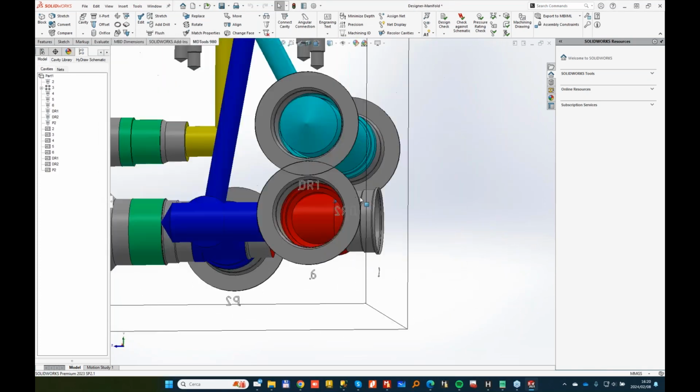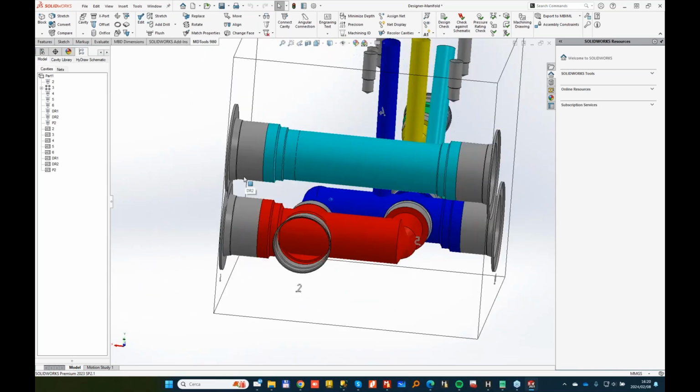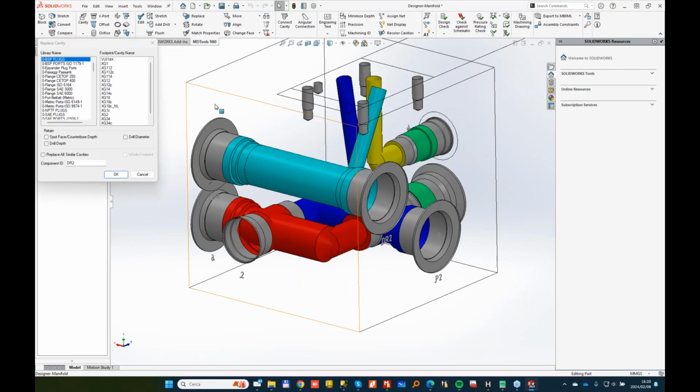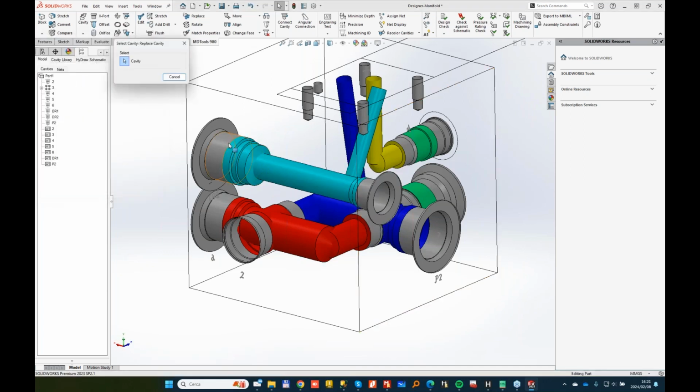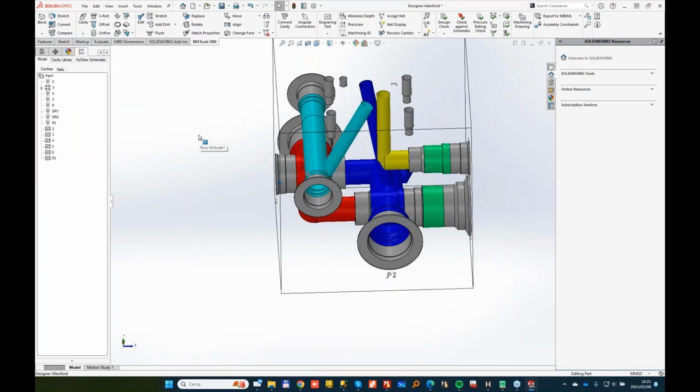Also reading the labels, I can see drain 1 and drain 2. I see a very large drill for the drain. So in this case, of course, I'll make a change compared to the diagram, but I'll discuss with the customer if it makes sense to use a different size. So I go for a short port. SA ports, I'll take maybe a -6 size, keeping the same diameter. And similarly, I do the same here, keeping the same diameter. Eventually, I can look for some optimization.